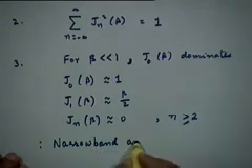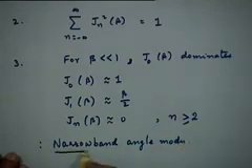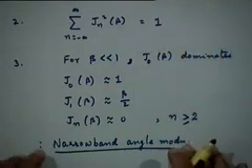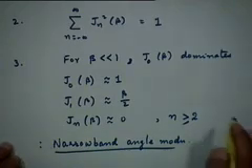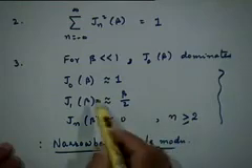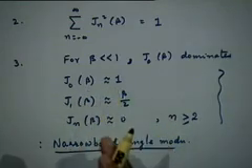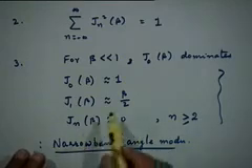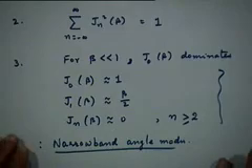Anyway, right now I am discussing only the Bessel function properties. We will come back to this point separately again. So these are things that you can prove, that J0 beta is approximately equal to 1 for beta much less than 1, J1 beta is approximately equal to beta by 2, and Jn beta is 0 for n greater than or equal to 2.